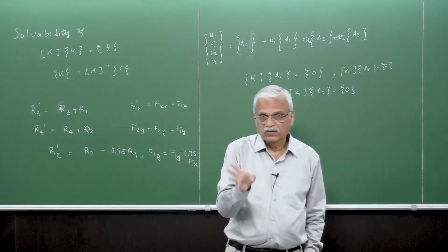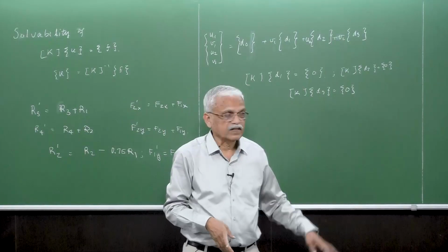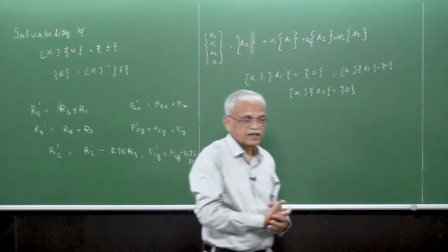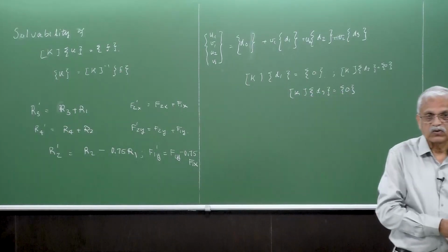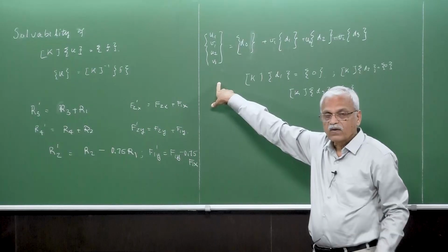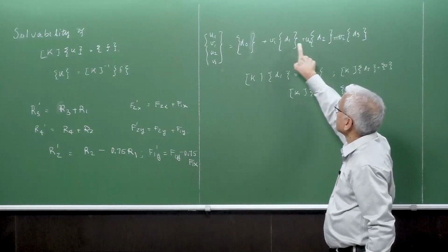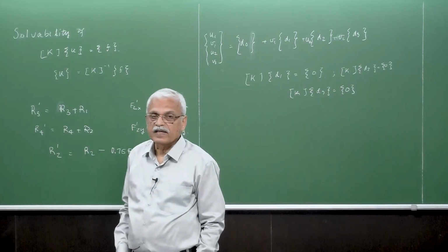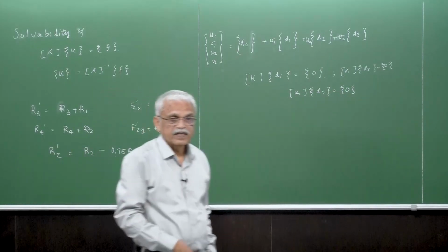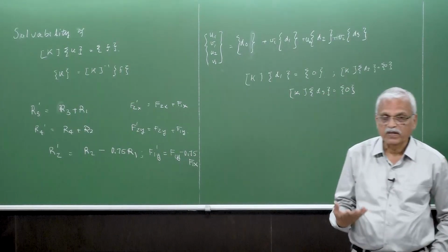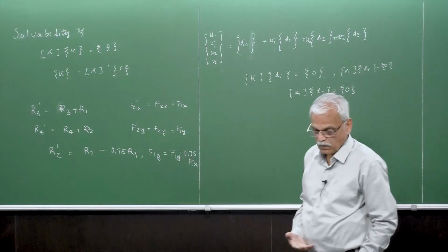So finally, what we can say here is that we have to apply at least three displacement constraints here so that you can get a solution. Okay, why do I call it a solution? That's because these can be changed as per your requirements to get the same amount of elastic deformations, or for that matter, the stresses and strains in the body, which will have the same value.